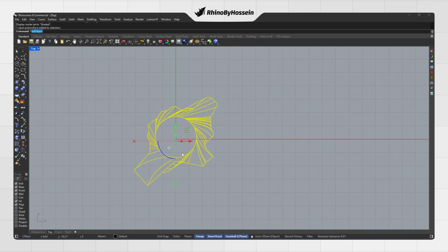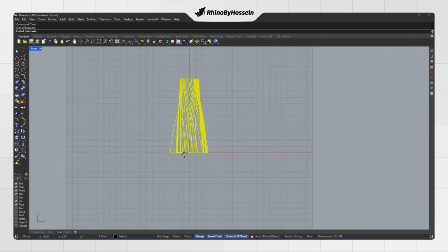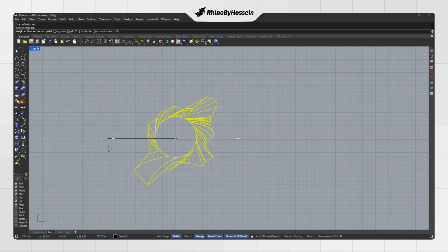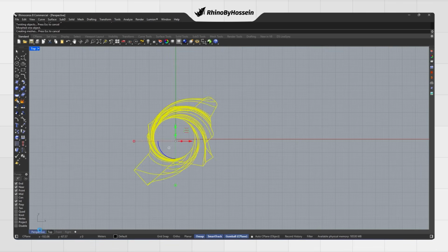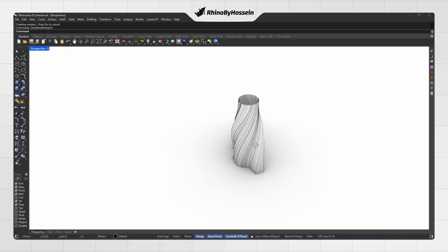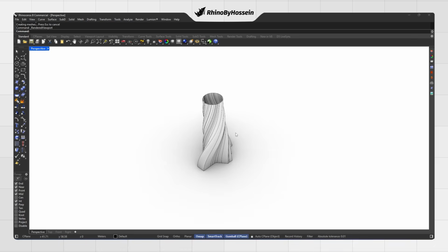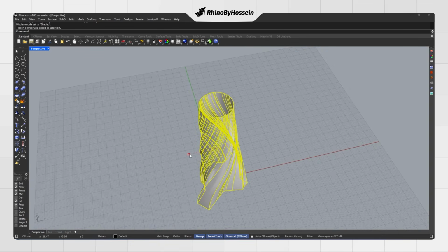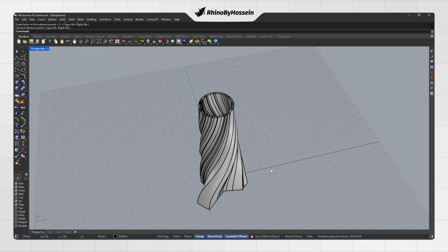And now, I'll use the twist command to rotate the form by 90 degrees, giving it a subtle sense of movement and rotation. Once this primary outer shell was created, I needed to give the form a more dynamic, terraced character, so I duplicated the surface inward. I did this by holding Alt and using the scale function with the gumball, creating a slightly smaller inner version.